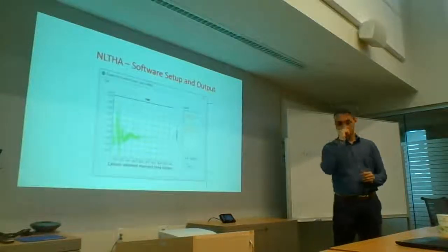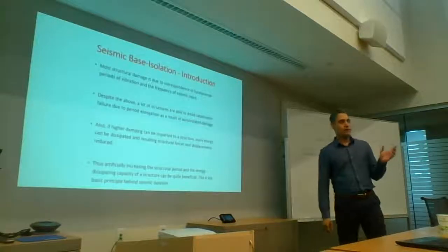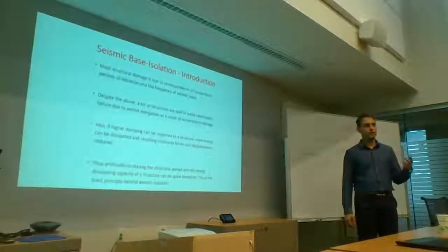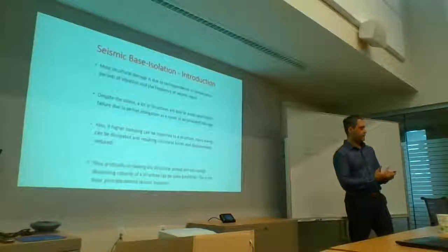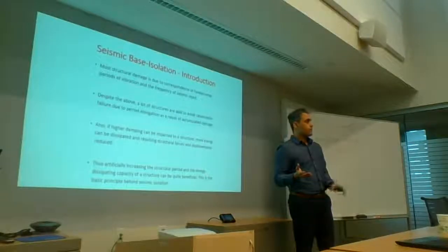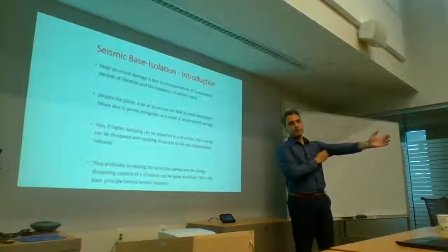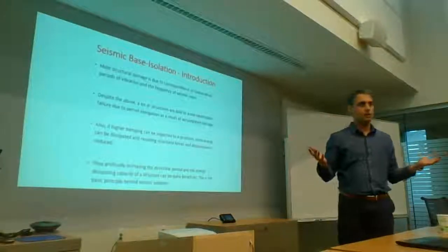Exactly. Okay, so why do earthquakes damage structures? It's really the fact that there's a correspondence of the periods of vibration of a structure and the frequency of seismic input. A very classic example was the 85 earthquake of Mexico City, which sits in a big basin.